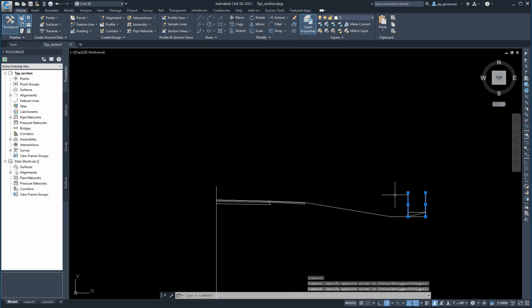There we go. And I don't need these construction lines anymore. They're gone. And you can extend this out if you want to, but that's a 4-to-1 back slope. And here's a 4-foot bottom side ditch. Quite often we start at 6-to-1 and then we'll drop at a 4-to-1 even faster and have our side ditch. Right? It's kind of your choice.